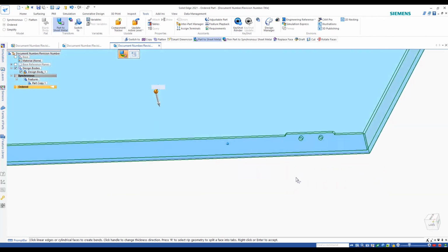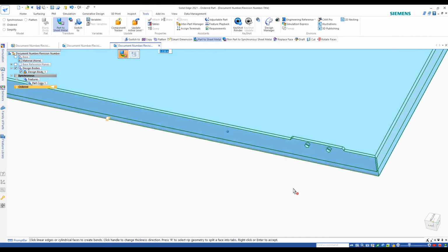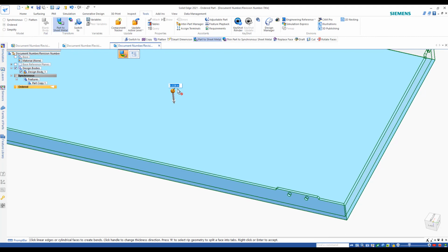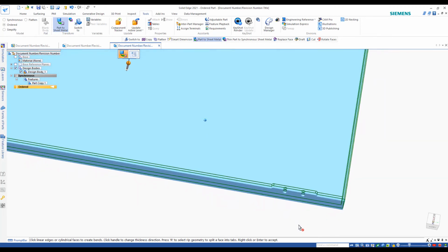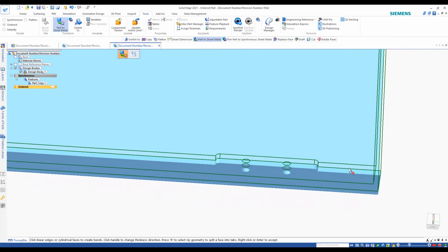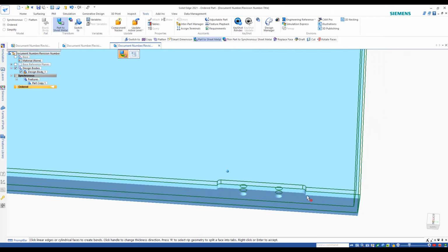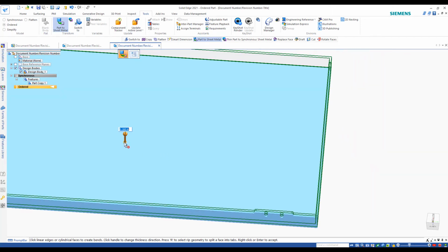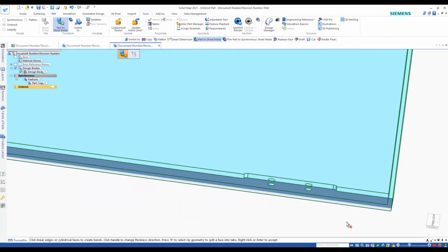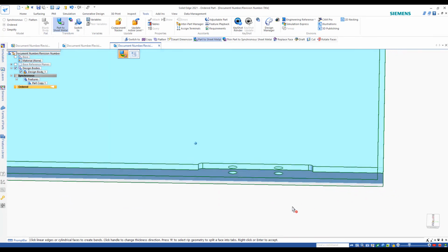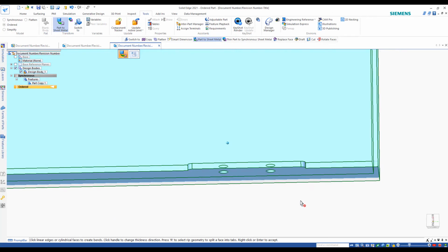It's trying to put a tab and then a bend at the edge that I selected. The other thing that you have to be aware of, and again, let's change the material thickness here to 0.16, is which side of that edge we are putting the material. So notice, if you look closely, it gives us a ghosted image of the original part and then where our part is going to be if we select this side. And so what I actually want to do is push this arrow and point it up so that it puts the material in the opposite location so that it matches the original.